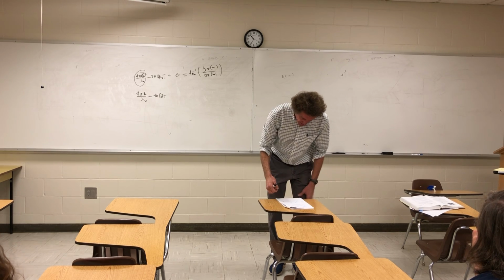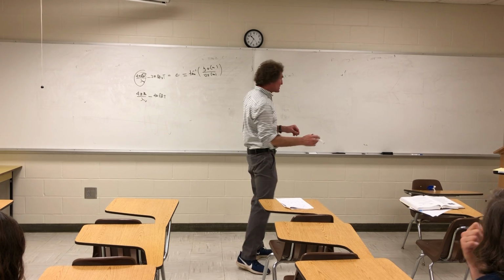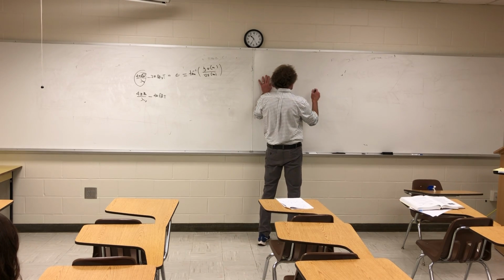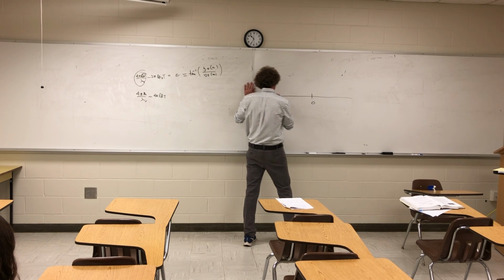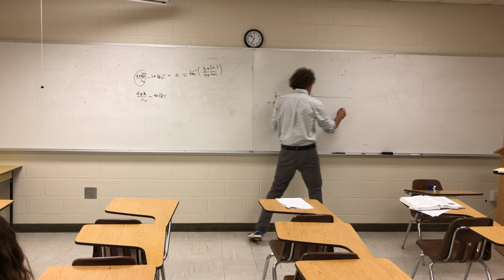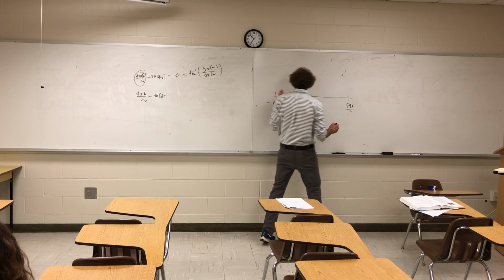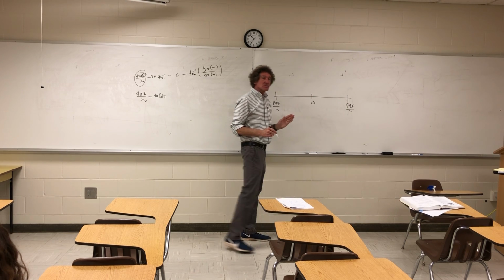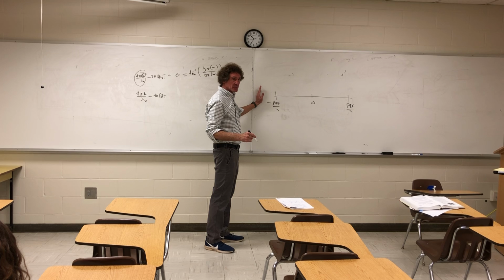Now, we talked about clutter, and we'll spend a little more time on that. But really, this is what happens when you're looking at the way they display data. Write this down, by the way. That's 0. This is minus PRF over 2, and plus PRF over 2. That's the maximum, actually the maximum spread. Because after that, any frequency we see up here is an ambiguous frequency. Y'all follow me on this?